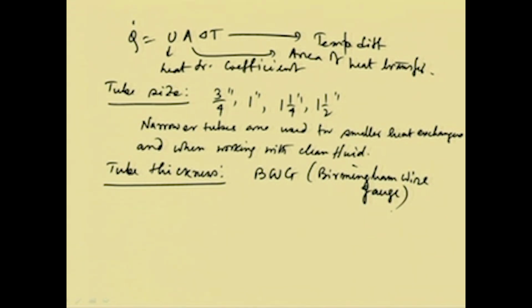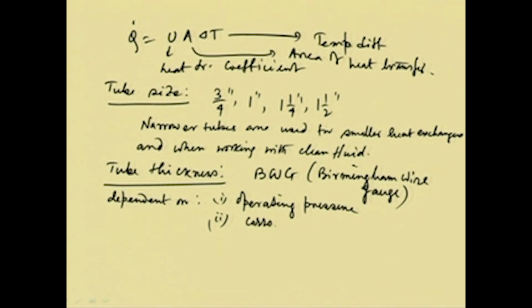This tube thickness is dependent on various factors. These are operating pressure, then we have corrosiveness of the fluids to be handled, and then thinning of tube wall during bending.